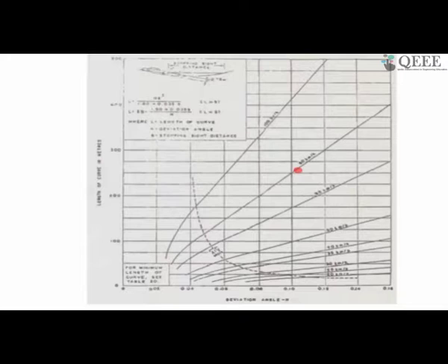So if you are at a higher speed than the speed which the curve is designed for, if you are on a summit curve, your vehicle can be thrown off from the road. And on the contrary, if you are at a higher speed than the speed a valley curve is designed for, when it is negotiating the bottom point of the valley curve, your car's suspension system can bottom down and can hit the bottom of the road.